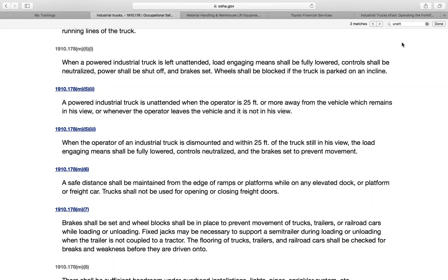And then we always have to use a spotter when we're moving an elevated load, right, with a telescopic forklift. Why are we going to use it? Because either it's going to obstruct our view or it's elevated, and then we have to worry about overhead hazards. Okay, so that's why. If you look at those sky tracks right there, perfect example on page 16. Yes, we've elevated the load, so we haven't obstructed our view, but now we have to be concerned about overhead hazards that we may miss.